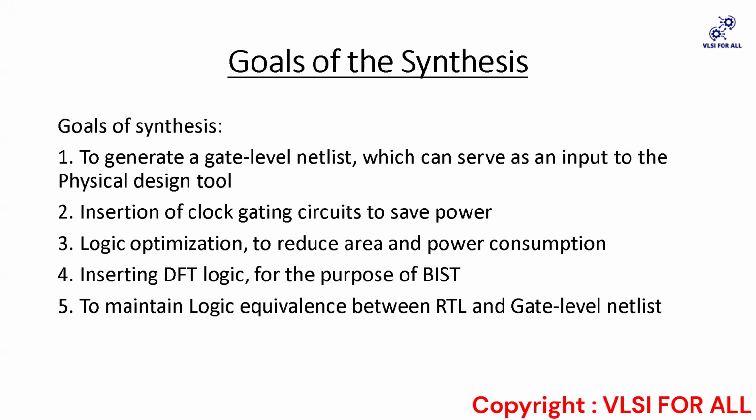The purpose is to formally verify that the synthesized gate netlist is functionally identical to the original RTL code. Because sometimes the synthesis tool can unintentionally alter the design's logic while optimizing it. It is unintentional, okay? But sometimes it can happen. So we cannot take any risk. That's why we do LEC checks. So I'll repeat it once again. The purpose of the LEC check is to formally verify that the synthesized gate netlist is functionally identical to the original RTL code. So these are the goals of the synthesis.